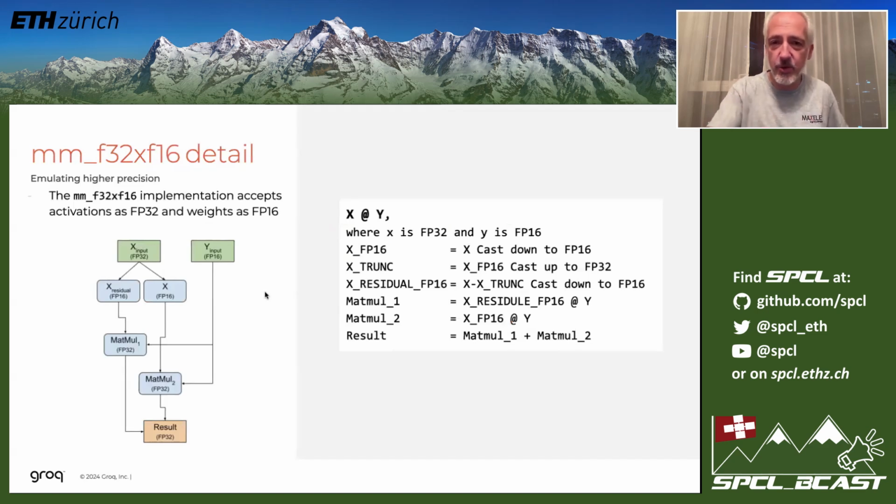Maybe before we do that, just to show the concept of the 32-bit floating point, which is really a combination of lots of 16-bit floating point computations. So it turns out that you can do 32-bit floating point by using 16-bit floating point. And we have here the way you have the 32-bit input. It gets split into 16-bit. You have a matrix multiply of two 16-bit floating point numbers, creating an FP32. You have another one with the lower half, and then you concatenate to get the result. So very nice. One 32-bit can be done with two 16-bit floating point multiplications, as long as they generate a 32-bit result, of course, each. So that's very good news. And a lot of combinations and things can be done with these units.